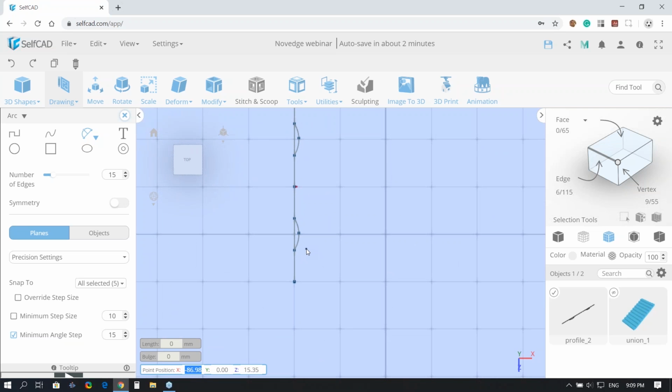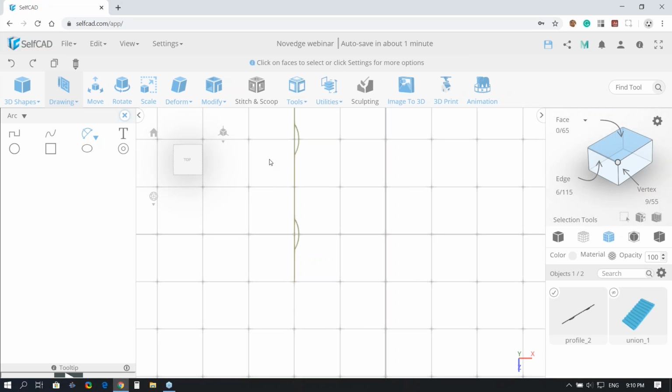In most applications, if you want to remove these details over here, you would need to go to a trim function, a function called trim. In SelfCAD, you can use the polygon selection, which will allow you to select by finding minimum cycle polygons. In this particular case, the minimum cycle was 1 line. In many cases, it could be bigger arcs. For example, if you want to select the entire arc, you see the minimum cycle will find the entire arc.